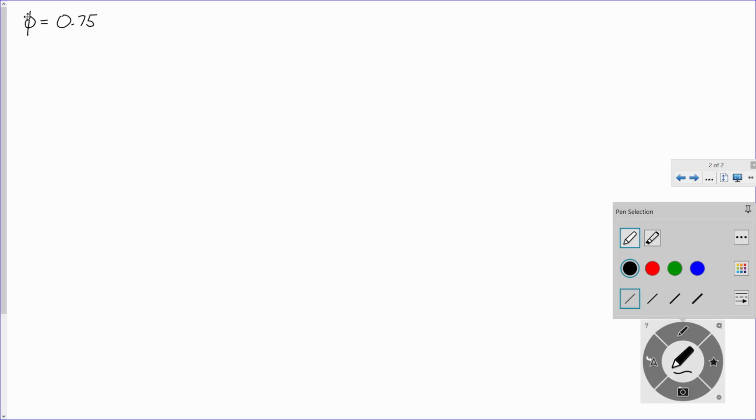Now, we're trying to calculate phi Vn, so phi Vn is our goal. How do we calculate Vn? This is really going to be plug and chug. What does the manual say on the second page, page 154? Vn is Vc plus Vs. Now, how do we calculate Vc?